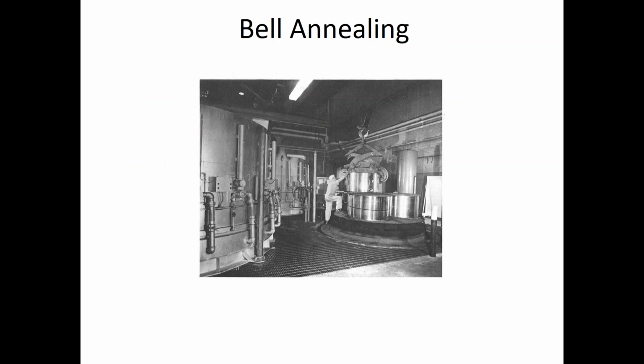Well, there's 2 types of annealing. Everything's complicated. Bell annealing, and here you see a gentleman loading a whole series of coils of various thicknesses into a base, and he'll stack them up to a certain level. Then there will be a cover. To the immediate left in this picture is a covered base into which all these coils are sitting.